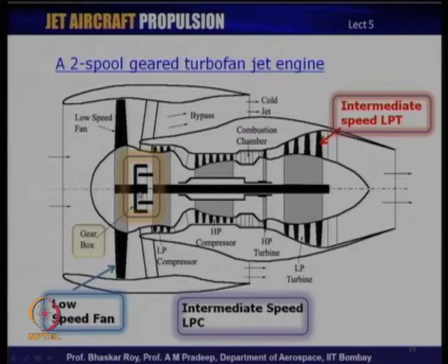So, this is a mechanical combination which many of the big turbofan designers have adopted, a geared turbofan, and this allows them to go to very high bypass, so all the benefits of a very high bypass can be obtained by producing this kind of engine. You need a gearbox now, very similar to turboprops or turboshafts, to run the turbofan. So, now we have gearboxes not only inside turboprops or turboshafts, but also inside the modern turbofan engines.